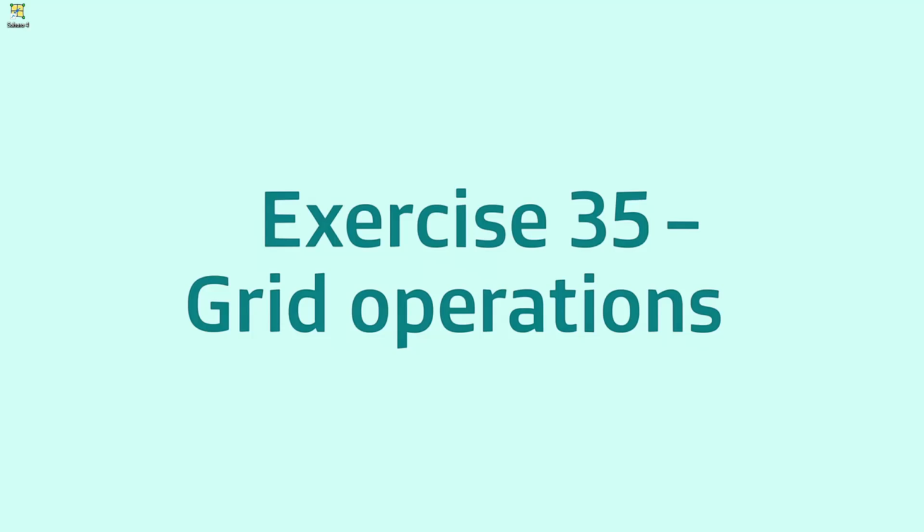In this exercise, we will use the tool grid operations to create, from two previous maps, a new map of a calculated variable. In general, grid operations can also be considered map operations, which are going to be used to generate new grids by means of equations or relationships between other grids, or also other variables or constants that can also be defined.